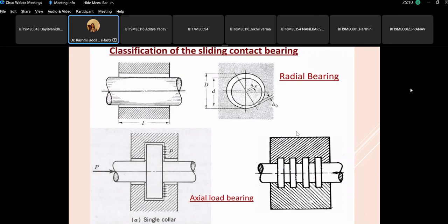Gears, specifically, can you tell me? Helical gears, yes. In spur gears, we know that it's only radial load. But in case of helical gears, in case of worm and worm wheel, you will also get the axial component of the load. And if there's an axial component of the load, then this journal will start moving axially inside the bearing.